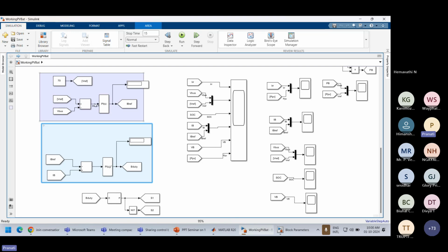See, at this PI controller, when we are using the PSO algorithm, before this PI controller, at this point, can you see the pointer? Yes, ma'am. At this point, we can use an ITAE index or integral square error or any index. I used the ITAE index to find out when it is minimized, and it is represented in the PSO algorithm. When the ITAE is a minimum, at that point, the optimization technique will automatically give you the KP and KI values.